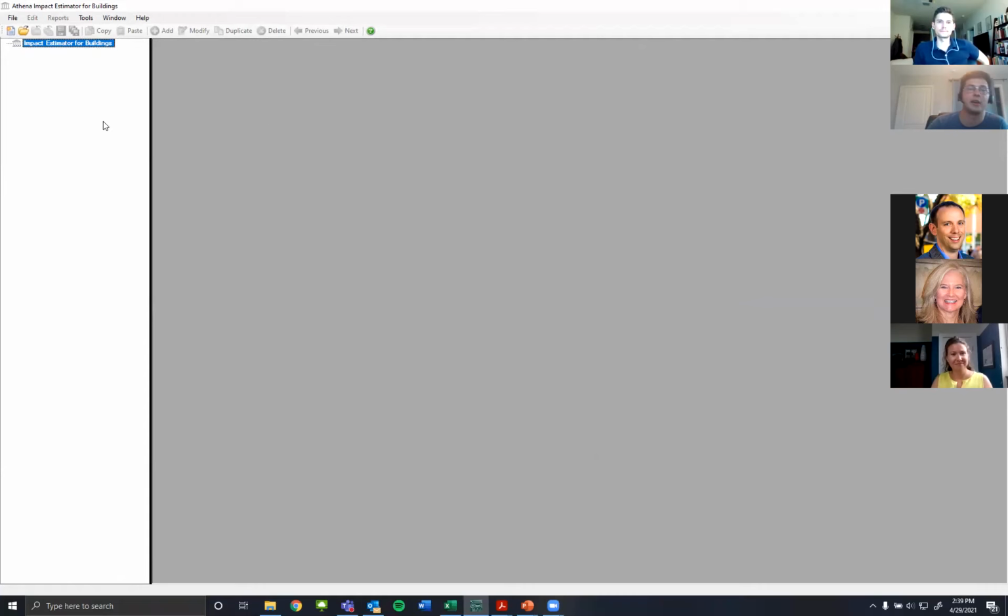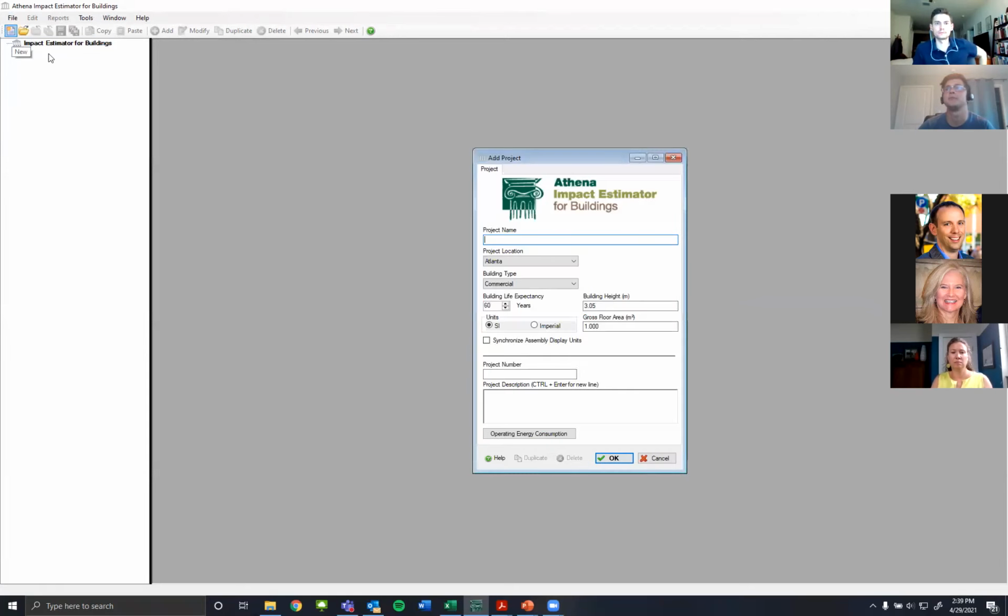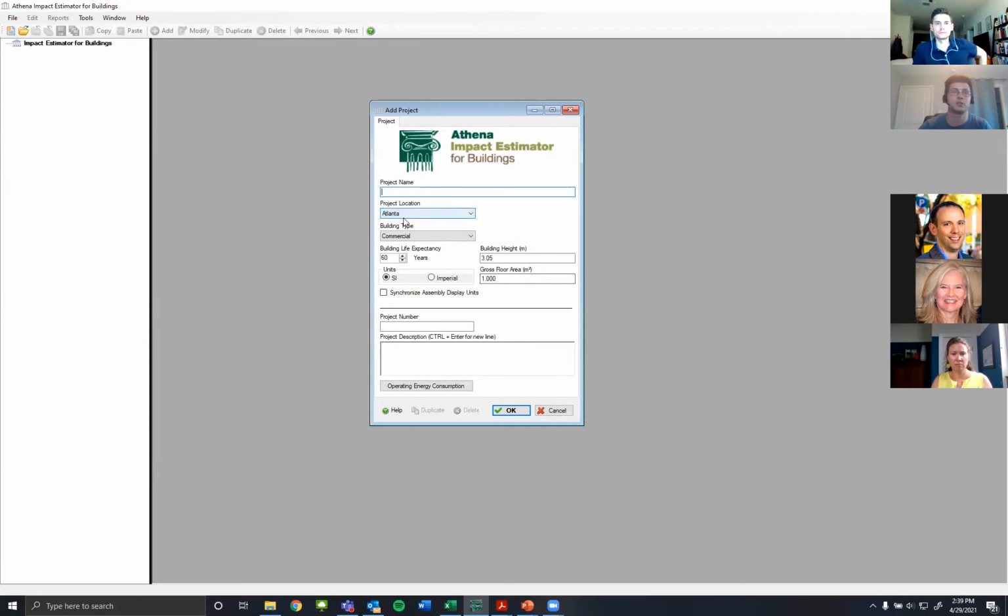So there's nothing open right now. And again, this doesn't connect to any BIM model or anything, but I just want to kind of go through creating a project, putting in the information, and a couple of different ways that Athena lets you do that. So create a new project. Right up here, you can do File New or click the New button. And then the first dialog box is the building information.